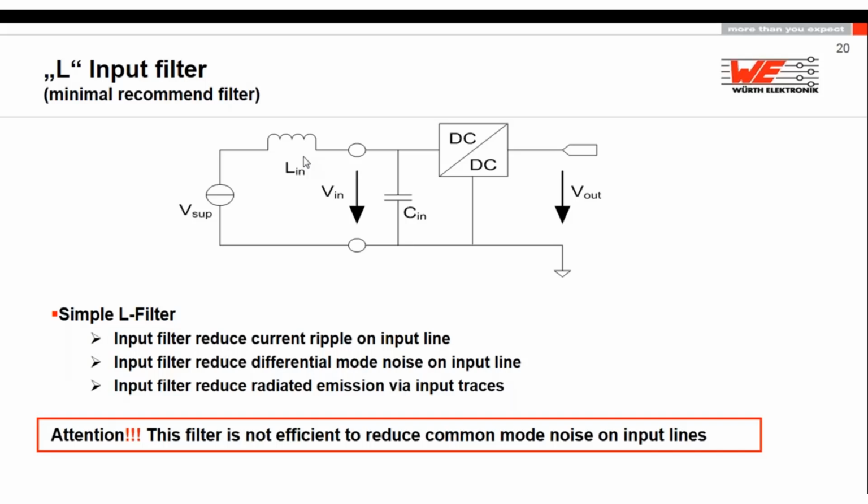So if you think about this inductance value, you can try, like I told you, between 2.5 microhenry and 47. But a good starting point: I always start with 10 microhenry, and then I see, okay, I need a little bit more filtering. Then I go up to 22, or if I have a high frequency issue, maybe the resonant point is already reached, so I go down to 4.7 and try in this way.